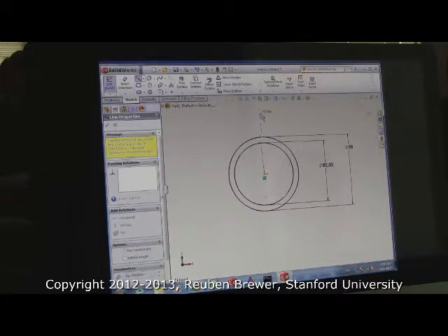If I go vertically, it tries to snap me to it. You see how when I snap, a little yellow and black vertical line appears? And now if I go down horizontal, a little horizontal line appears. And now if I go at a 45-degree angle, it tries to snap to that. This is SolidWorks trying to be smart. It will snap to 0, 90, or 45 increments.